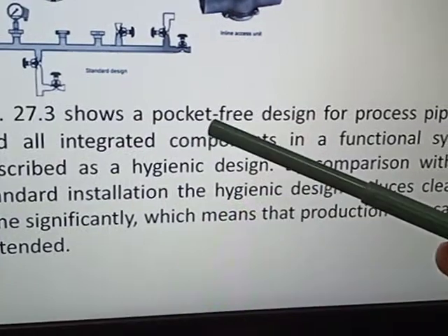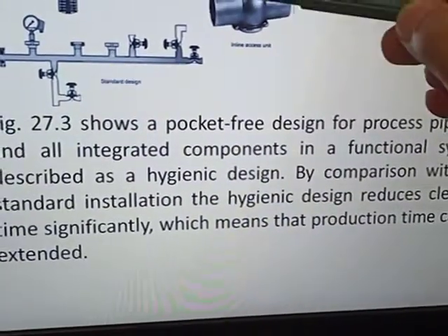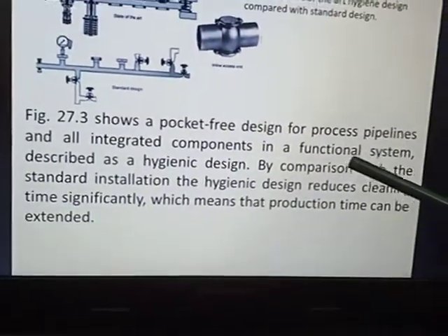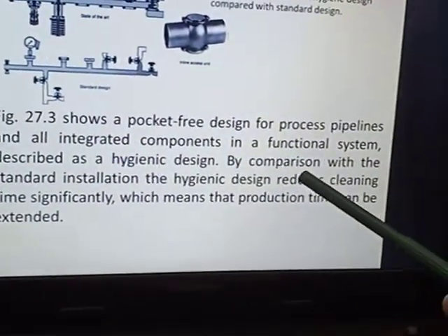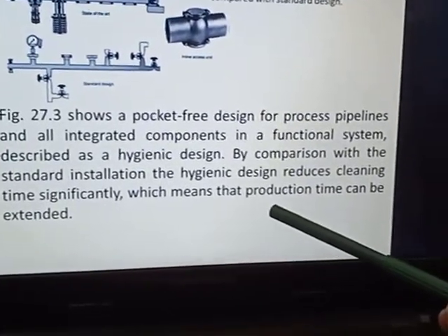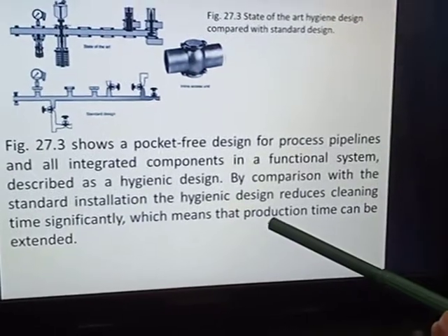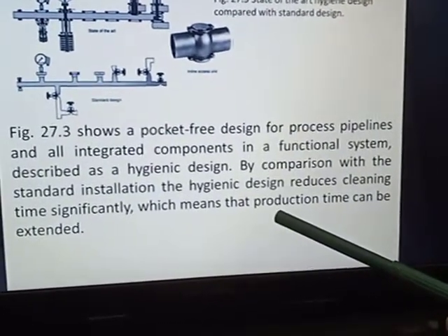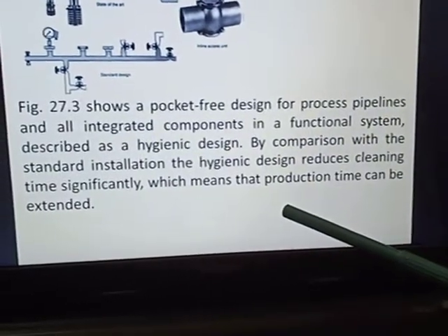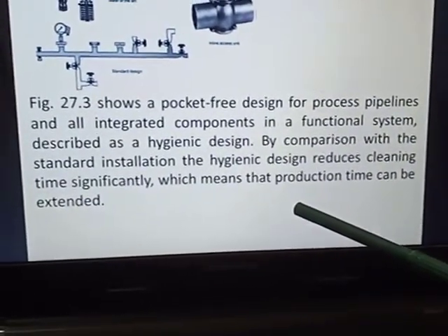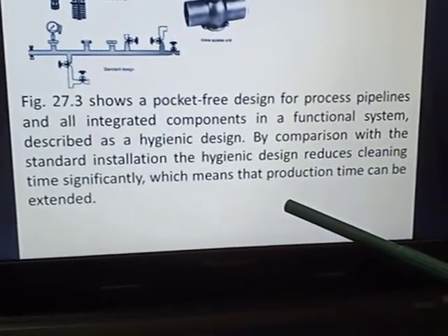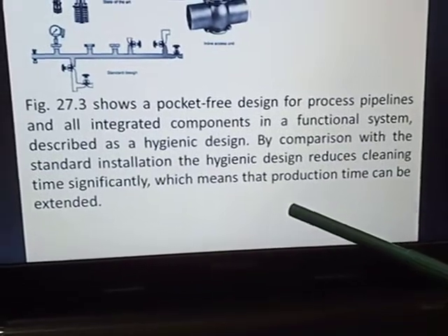This figure shows a pocket-free design for process pipelines, with all integrated components in a functional system described as a hygienic design. By comparison with the standard installation, the hygienic design reduces cleaning time significantly, which means that production time can be extended.